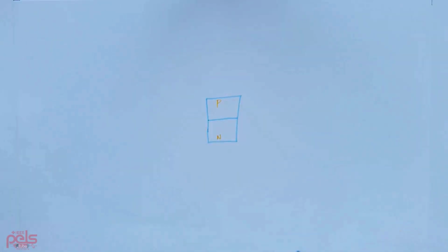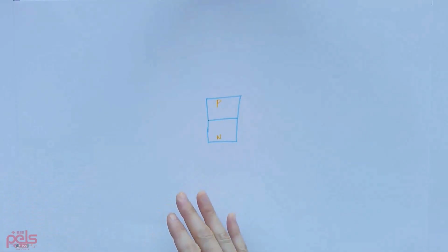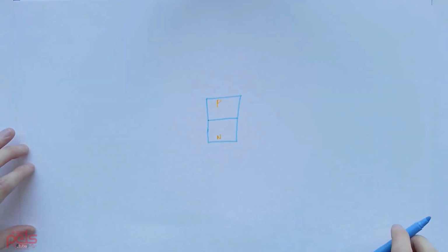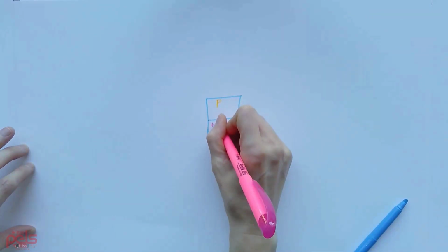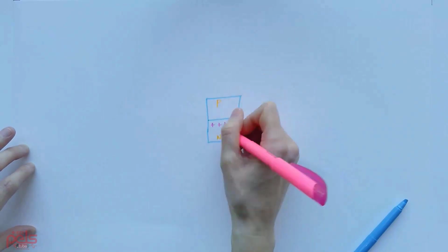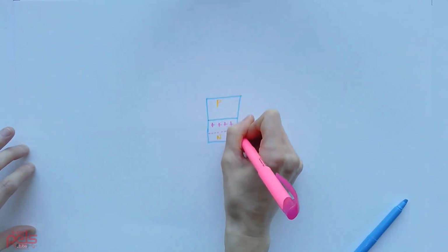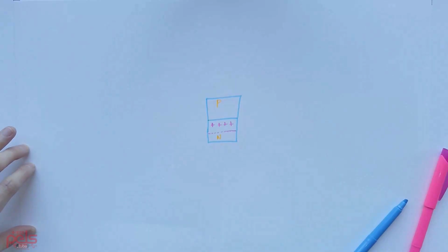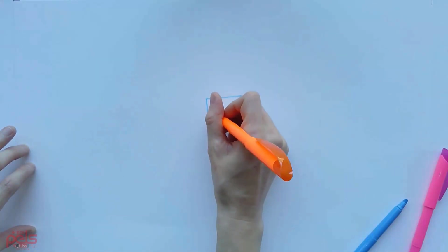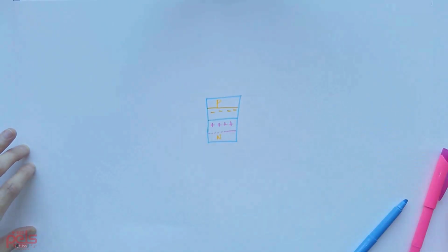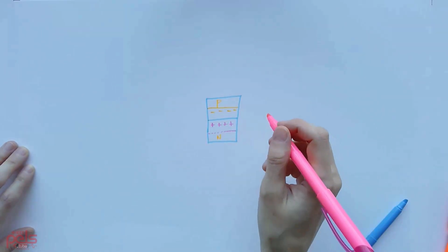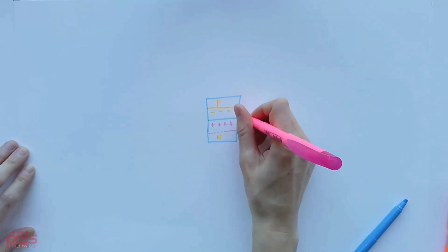And recall when we have a p-doped substance next to an n-doped material, they're going to form a little barrier. And we're going to have some positives from the p side go to the negative side. We're going to get a little depletion region here. And we're going to have some negatives as well that are going to come from the n side to the p-doped material. And what we get from this region is an electric field. So we have an electric field going here.